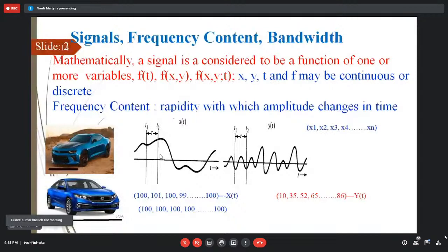The first question comes to digitize. If I take digitization, or discretization in time, at my own accord, will it be possible to reconstruct the continuous time signal back at the receiver end? The answer is no. We need to choose a rate of sampling. We need to make a sampling interval such that, from the discrete set of values, when required, we can reconstruct back the original signal.